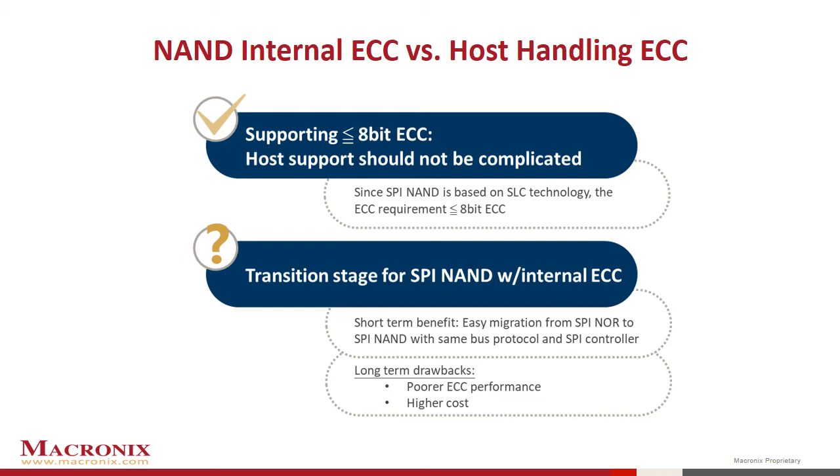Also, historically, NOR flash did not require error correction, so the host, for example an MCU, did not need an ECC engine. But moving forward, some NOR products may be required to support error correction to meet ISO 26262 ASIL requirements.